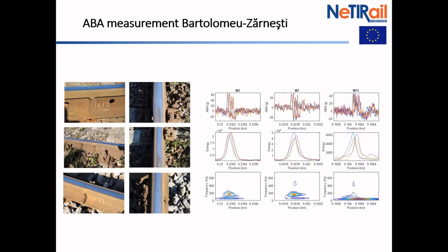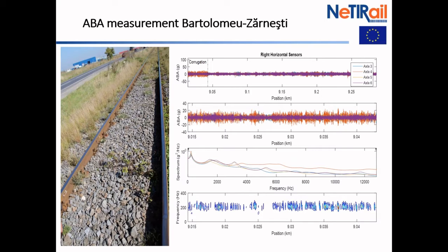That means that in case you need to do a replacement, you need to rank which of the welds you would like to repair later. Weld number 7 should have the highest priority because the highest dynamic forces are happening there. And so this is one of the analyses we could do.